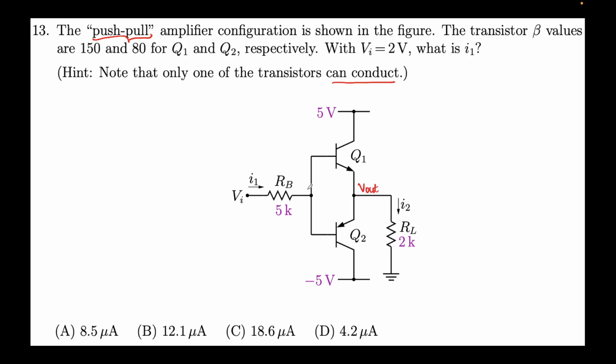Okay, in the other half, when let's say Vi is negative, minus 2 volts, minus 3 volts, this will be turned off, right? Because then VBE will become, sorry, in this case it's VEB. So VEB will become greater than, so this is the emitter here, right? We are taking the output from the emitter. Earlier in the previous problems, if you recall, we were taking output from the collector. Usually the RL was connected over here, right? But this time it's connected over here.